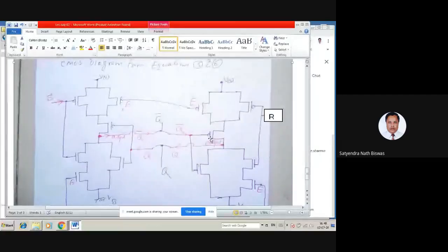In here this PMOS and NMOS get connected, that is q bar, and this is input, but actually this input is coming from the output from the left side. You see, q bar will be short circuited here, and output from this side will be q, and that will go to the input of the left side, right?